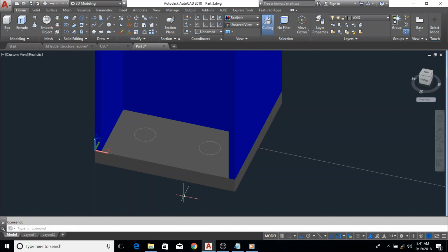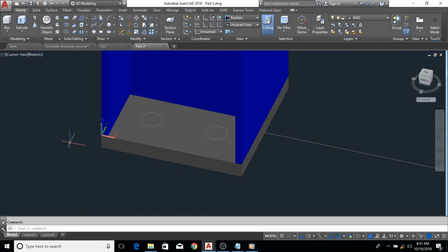Now the command that we normally use to drill these holes, or to create a void in the material, is press pull. The icon of press pull is right here. As I said earlier, if you are a newbie to AutoCAD, pay much attention to the icons for easy localization of them. Me, I prefer the shortcut so that I can make things a little bit easier and faster.